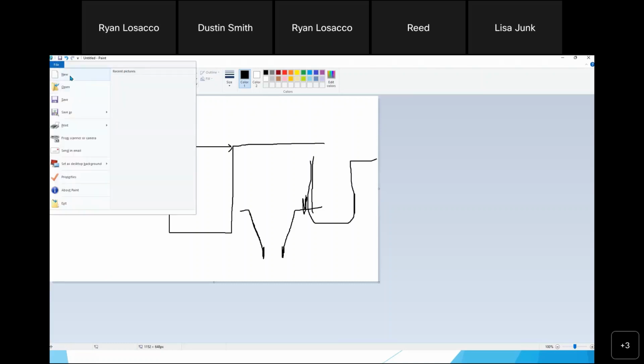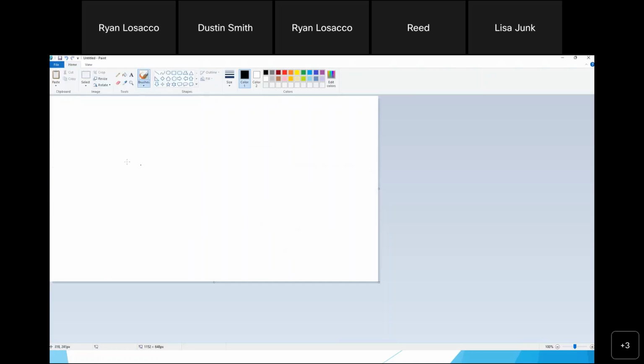the bottom of it. Here's another thing too, while it's on my mind, is if we have this blind hole, depending on your manufacturing process, I know this won't be for every instance, you'll probably have a tooling mark at the bottom. And we want to measure from here to here. We don't want to measure this depth on here.